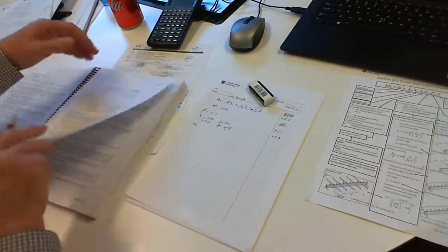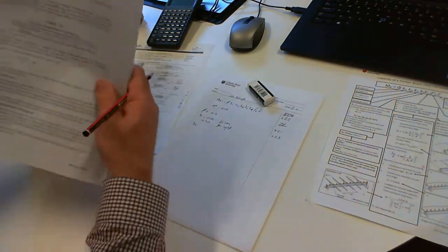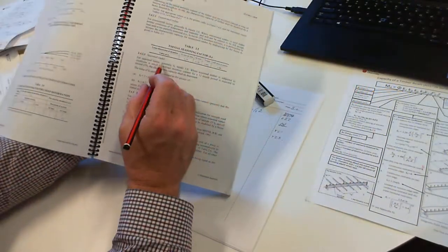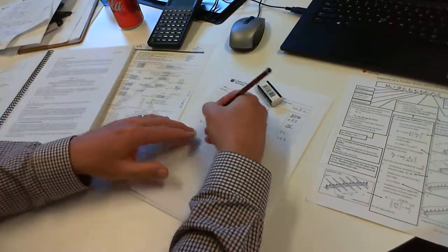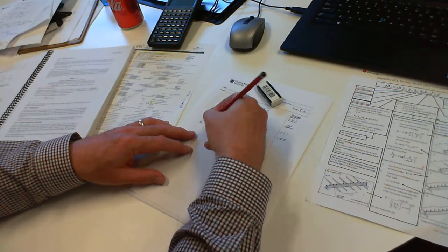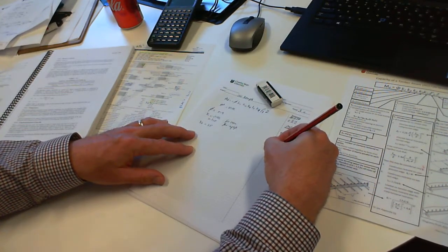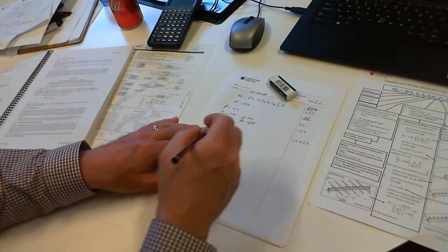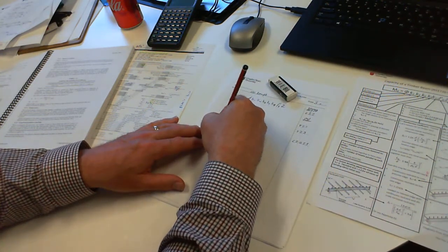K4 is the partial seasoning factor. When we're using seasoned timber, K4 generally equals 1. It's only otherwise when we're in a very damp environment where the timber is actually going to get wet and unseason itself. So that's clause 2.4.2.3, K4.